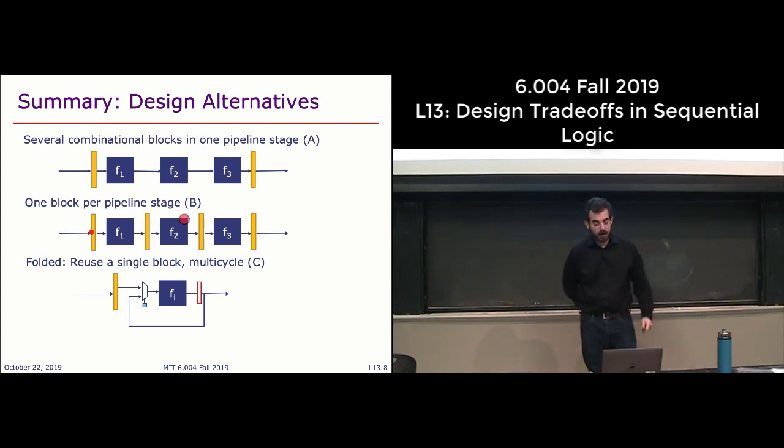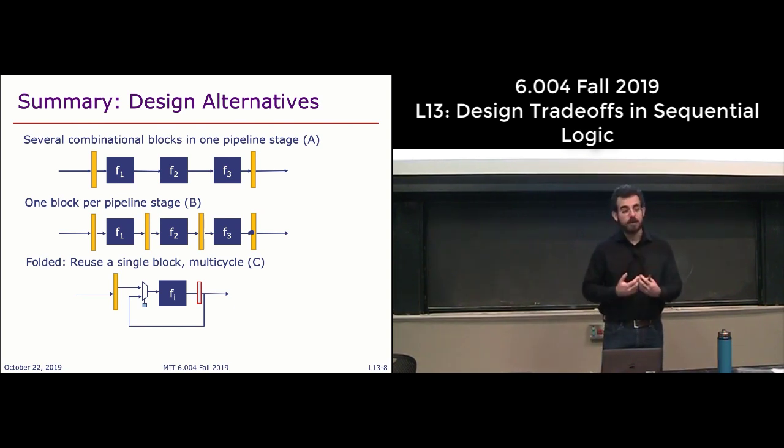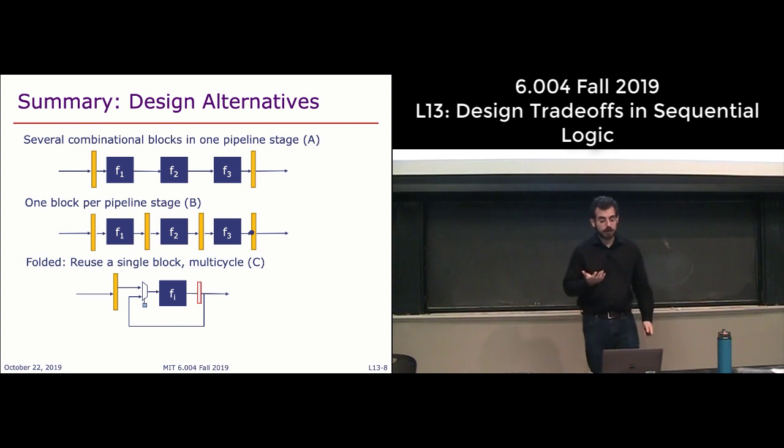In a pipeline, on the other hand, as you can see here, what happens as clock cycles go by is that we start overlapping multiple elements, right? So this stage is processing the blue element over here, while this stage is processing the green element over here, while this stage is processing the red element, right? And so we're getting one output per cycle. And the key benefit is that we now can reduce the clock cycle time and increase the frequency, and so get more outputs per second.